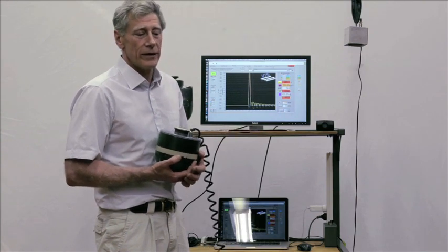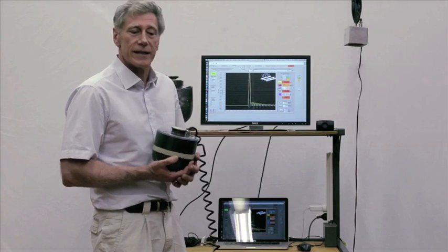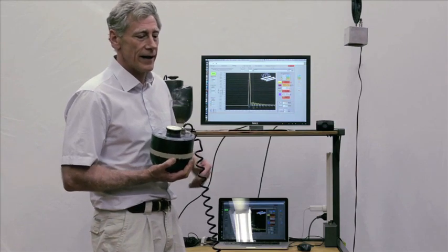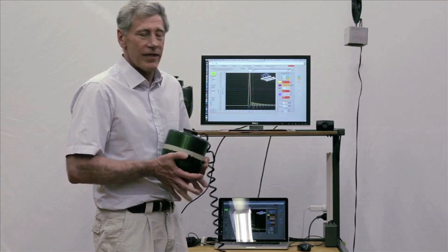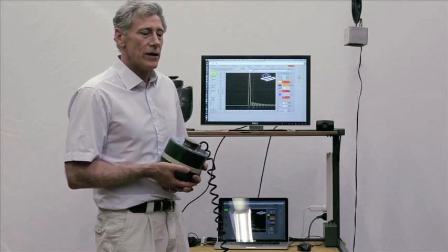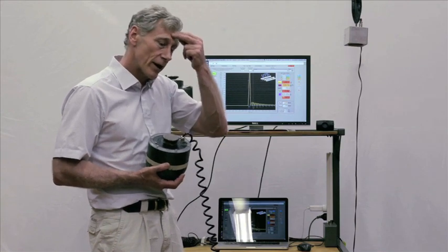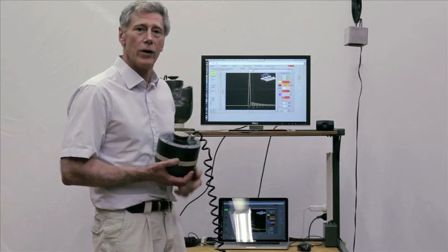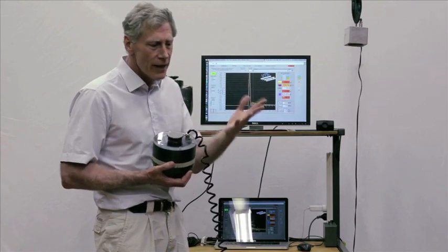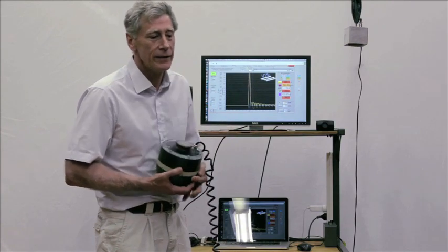And they've plotted data against acceleration, and they've found that at 1,000 HIC or 200G, you've got a 3% chance of death if you're a white Caucasian male and you get a frontal lobe impact. So that's our pass-fail criteria.